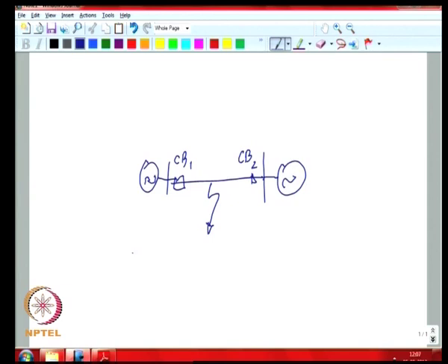If you look at the traditional distribution system, you might have a breaker at CB3 and say you have a fault somewhere down on the feeder, and you have to open just one breaker and you can actually clear the fault on the feeder, which means that there is actually a lot of simplicity over here. The protection equipment is actually reduced by half in this particular case. You need just one breaker compared to multiple breakers in the other scenario.